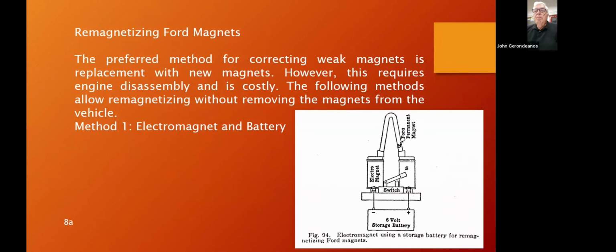And there's a bit of a controversy. Some people say that you magnetize on the rising field, and some say it's on the collapsing field. And it's not that straightforward. When you put voltage across an inductor, the inductor contains capacitance, and it's an oscillatory rise and also an oscillatory fall. The current doesn't just flow smoothly.